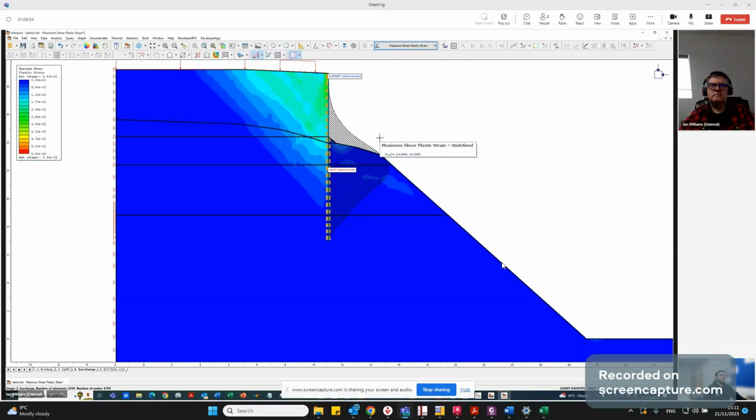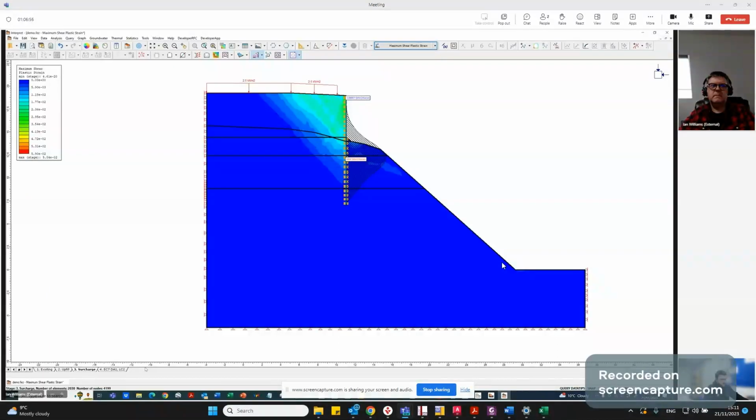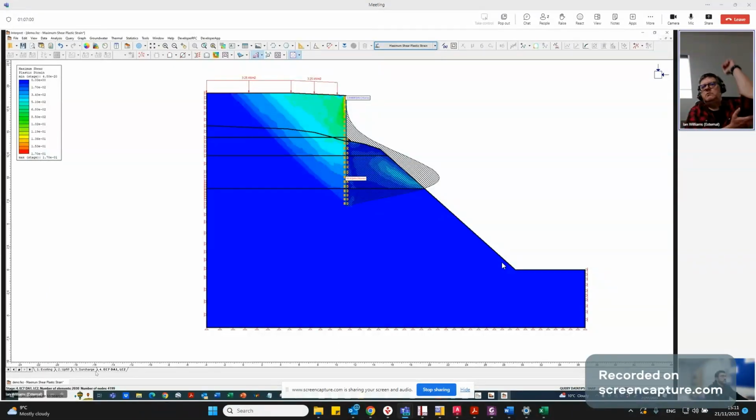Wow. Yeah, it does. It does when you apply combination 2. It's crazy. But would you design your piles for that? There is a discussion in Eurocode 2. It says you have to check for both. If you use combination 1, you will have maybe 200 kilonewton or something, or maybe 210. But in combination 2, it gives it twice as much sometimes or more.